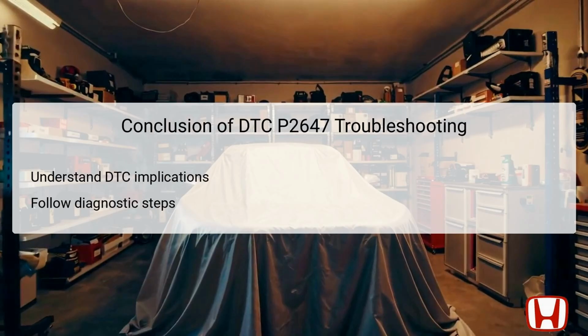In conclusion, addressing DTC P2647 requires a comprehensive understanding of the vehicle's rocker arm oil pressure switch and its role in the VTEC system. By following the outlined diagnostic steps, technicians can systematically identify and rectify the issue, whether it be a faulty component or an electrical connection. It's essential to perform thorough checks, like monitoring oil levels and conducting proper tests to ensure that all aspects of the system are functioning as intended.